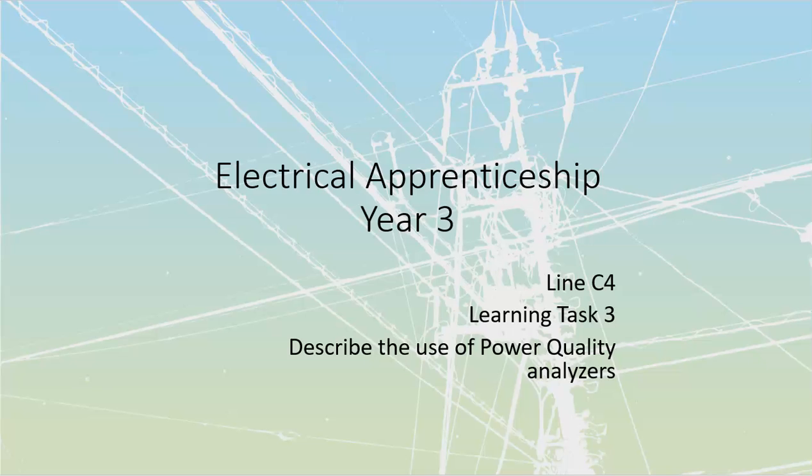For a number of years, there was really no standard. Then after a while, the IEC 61000-4-30 Class A standard was adopted. It's a standard that talks about what a power quality analyzer should be able to do, what sort of parameters it needs to have, for sampling rates, repeatability, export of data, things like that, that are all going to be placed inside of it. So when you buy yourself a power quality analyzer, as long as it's compliant with that, you're going to be getting something that will be able to do the bulk of the work for you. You just need to put these things in, and you have to put them in properly. Like any other tool, if you misapply it, it's not going to do much for you.